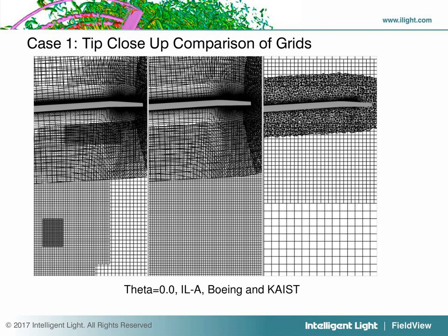On the right is a submission from CASE. So you can see here the near-body grid is an unstructured tetrahedral mesh overset onto structured Cartesian meshes. So these are examples of 3 types of grids that were submitted for this workshop.